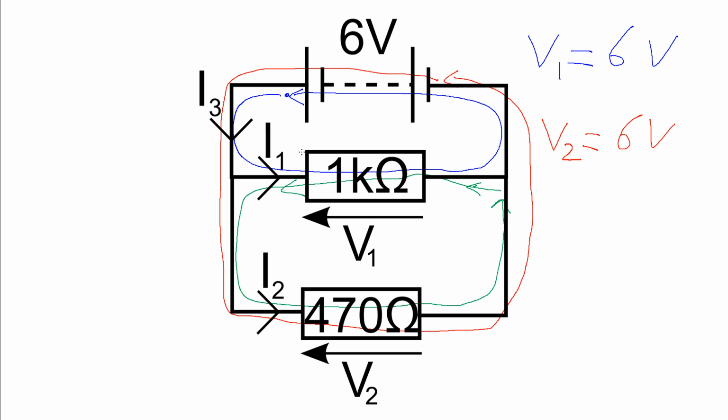So if charge passing here loses energy, then going backwards is the equivalent of gaining energy. If we go backwards through a resistor, that counts as an EMF. If we go backwards through a cell, that counts as losing energy. So around here it still applies because we're going backwards through this resistor, and so that counts as a negative 6 volts against the plus 6 volts here, which gives us 0. So it still applies, we just have to be careful about the direction we're applying it in.